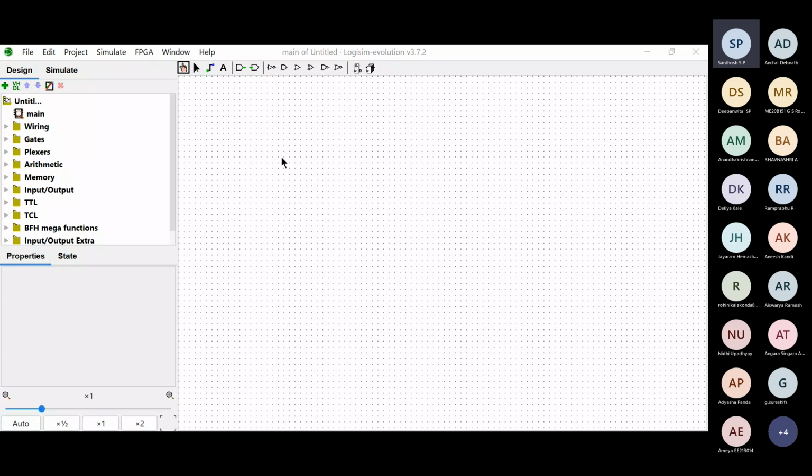Okay, so now if we move to this expression column, it automatically generates all these expressions for us: c equals xy, and s equals x'y plus xy'. It automatically generates the K-maps and minimizes it. We just have to give the input variables, the output variables, and enter its truth table. So it basically does everything for us.